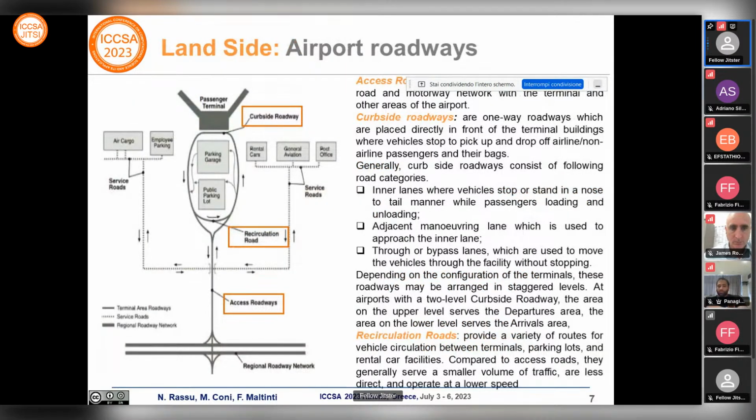Traffic on airport roads differs significantly from that on ordinary roads due to the highly restricted geometry, the different traffic composition, and the travel expectation. There is a difference between traffic conditions within the same landside. The access and transit road network is characterized by traffic flows with a driving style typical of rural areas, while the road network of the landside area is more akin to that of urban areas, both in terms of low travel speed, the mix of traffic composition, and the multitude of maneuvers permitted.